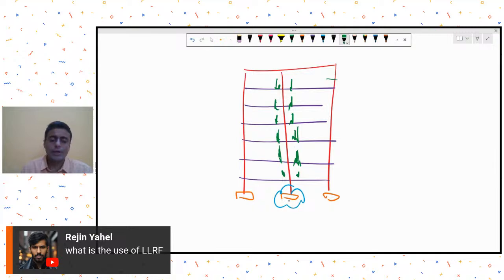So if it is quite rare, the concept is then why should I design this footing for the full live load? Why not design my footing only for a part of it? Or why not design this vertical member only for part of that live load? For a horizontal element, we will design it for full live load because during the design life, it is possible that at any instant the full live load may be present over there.